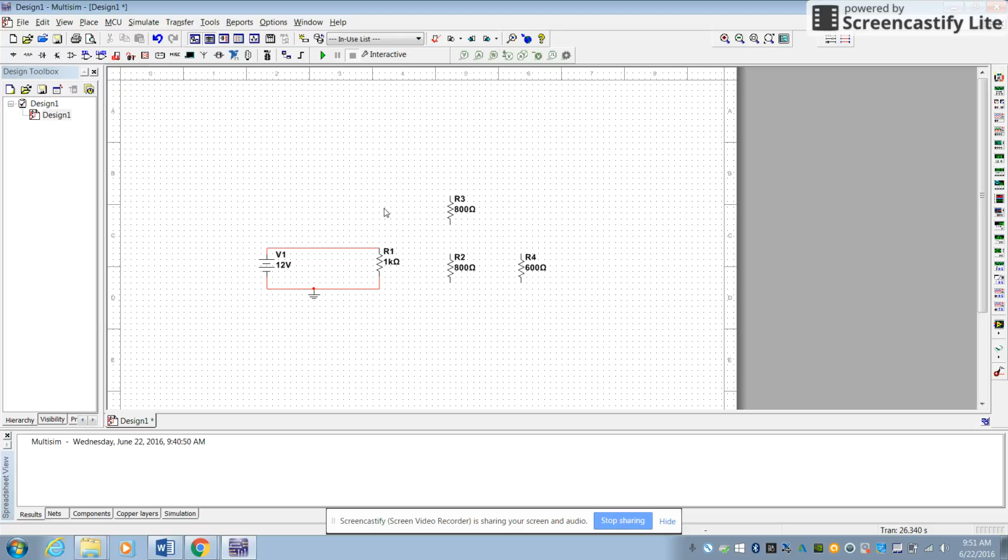Okay, so now we've got all these new resistors in there, and you're going to notice if I click on the edge of my old resistor, I now have a problem. It's not the same symbol, and it now takes that wire away from my old resistor. The solution to that is to get a junction in play. What I do is hold down Control and hit J.